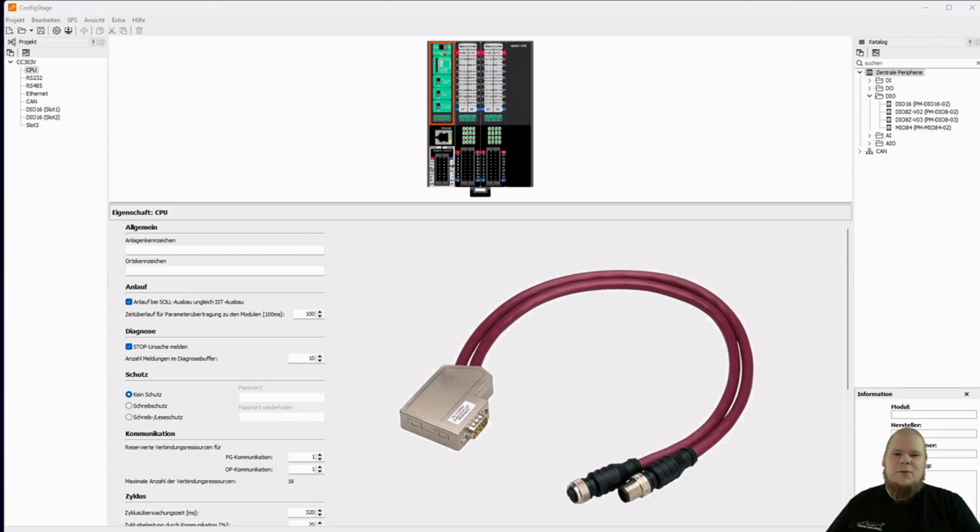Only Profibus V0 is supported, not version V1 or V2. A customer had made this mistake. He had selected V1. He searched for wiring errors for a really long time until he called us in despair. We were able to explain to use V0 to him again. Again, to mention, we are not an iDevice. That means our Profibus device cannot act as master and slave at the same time.